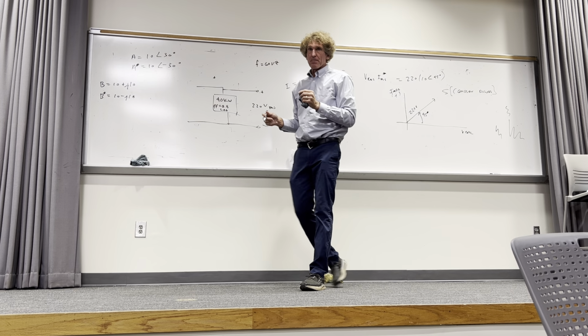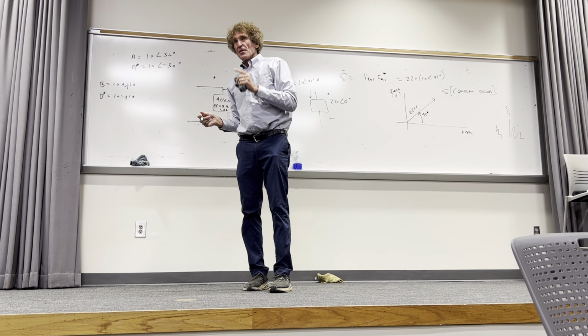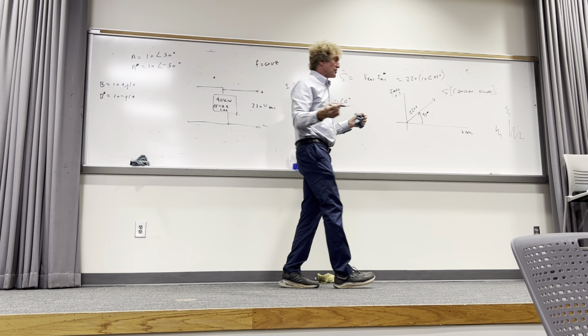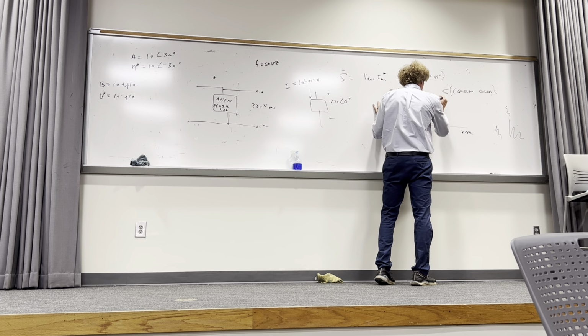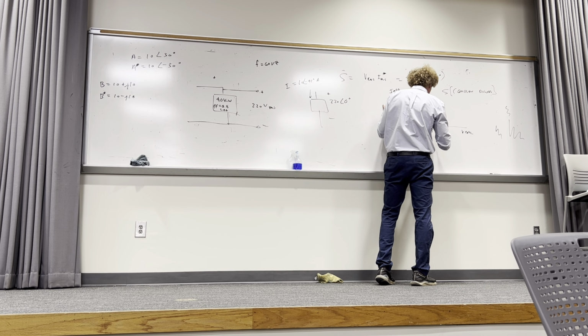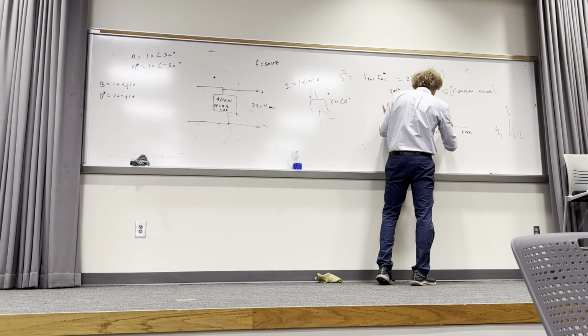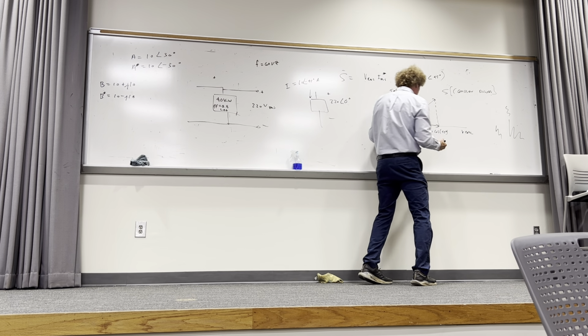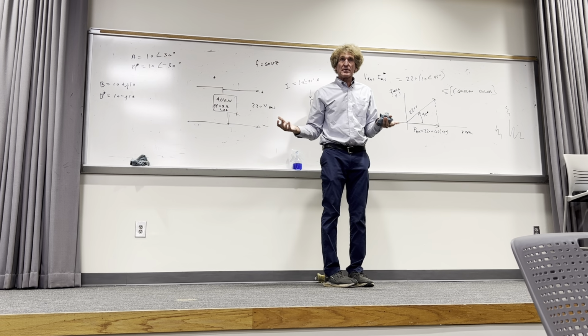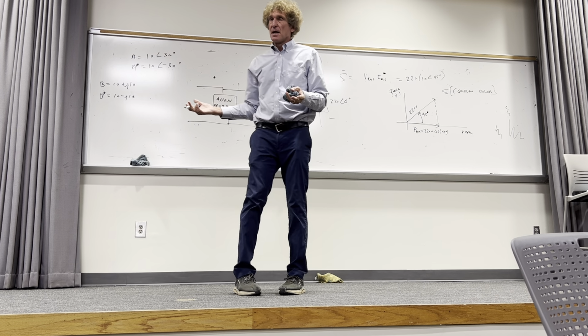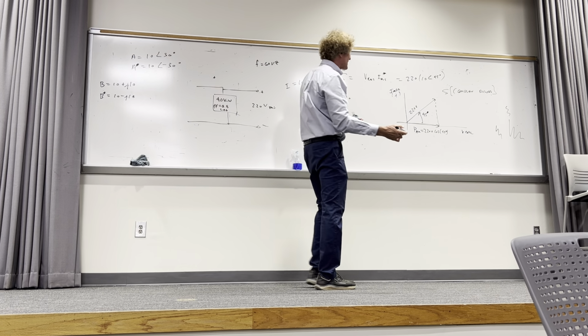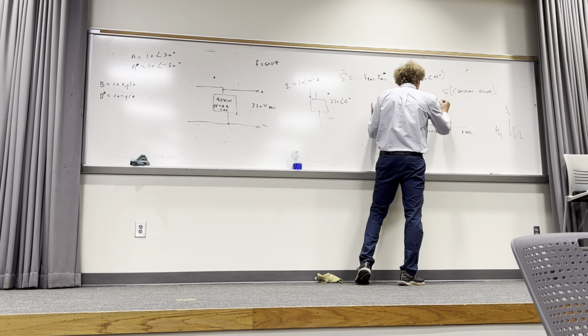Do y'all follow me? Now, the real power that you're used to is on this axis. If you take the projection of this vector here, this would be the average power, and it's nothing more than 2,200 times the cosine of 45 degrees. That is the real power, the power dissipated. But there's something termed the reactive power, and it's this guy right here.